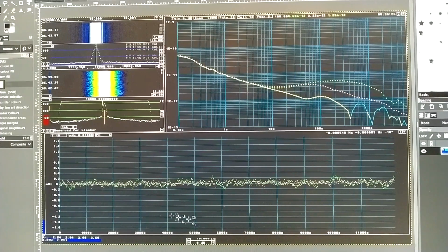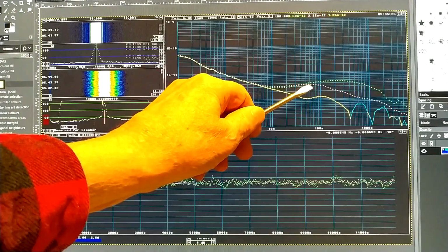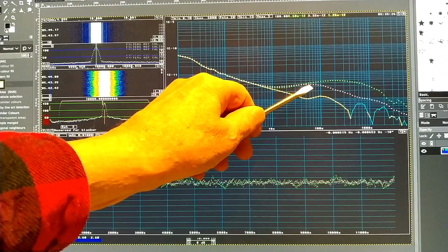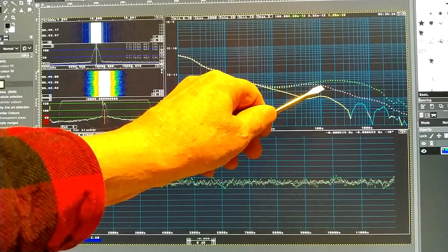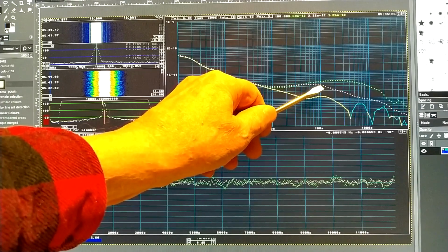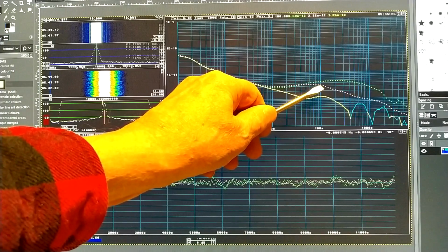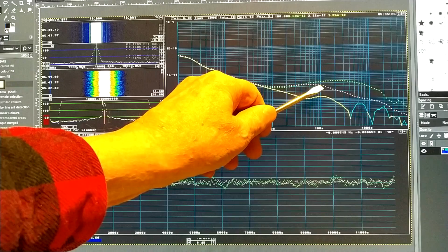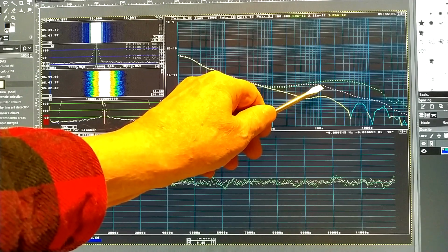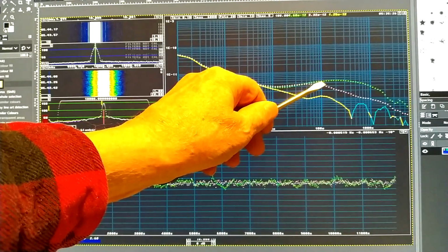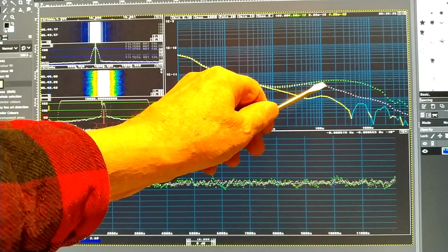Here, both PLL resistors are set to 4.4 kilo ohms. And I can compare it with 10 kilo ohms. If you look here, it bends down at about 50 seconds. Means that at 100 seconds, the red channel is modulated by the noise of the rubidium oscillator, but the noise that it produces itself is attenuated. And of course it has to be the same also in channel 1, but it's more difficult to see that.